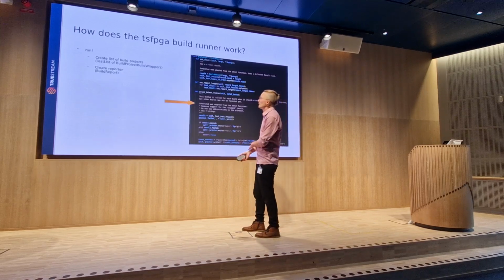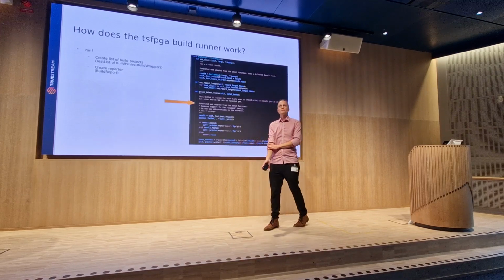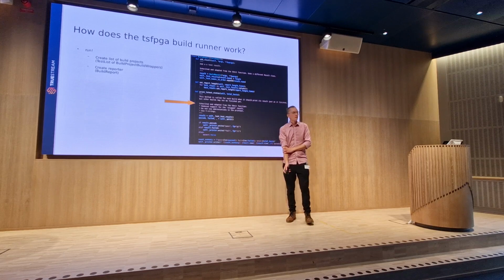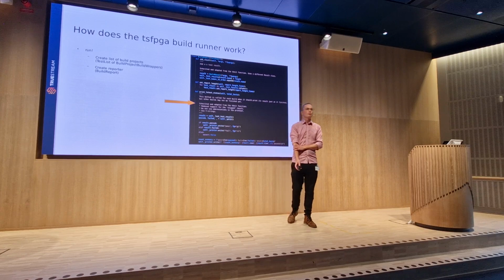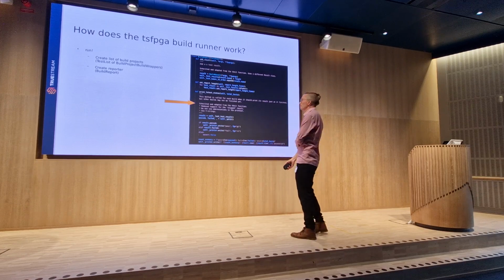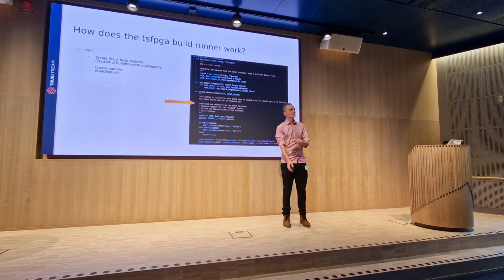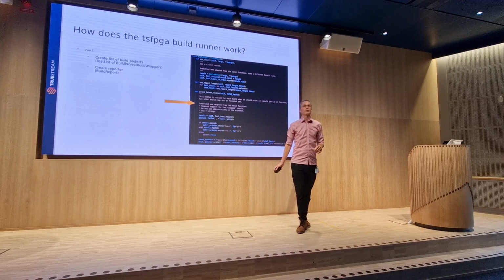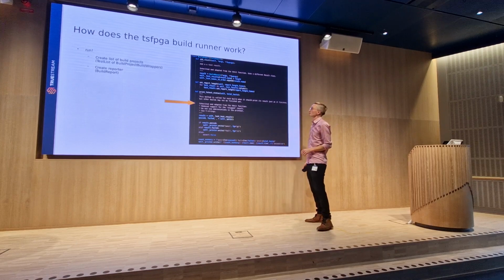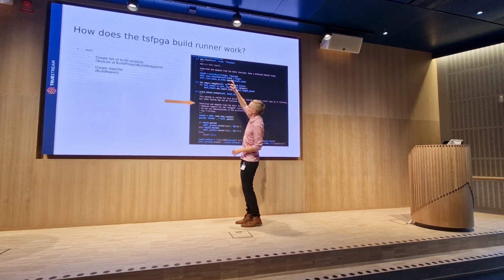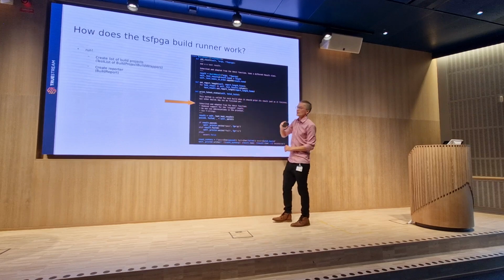And then we need a reporter. Instead of using the VUnit test reporter, we use our own build reporter. The major difference being that we like to report things a bit differently. We have more results that we wanted to print. So, based on the test report class, it's these three functions that are overloaded.